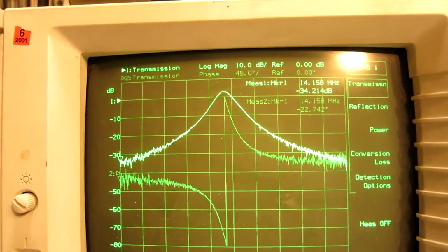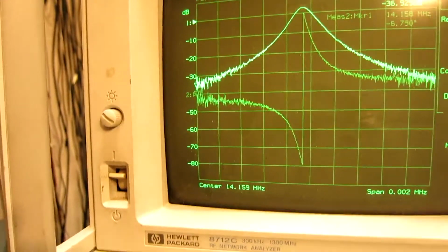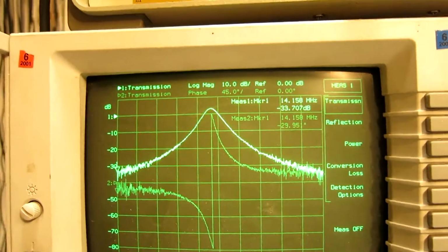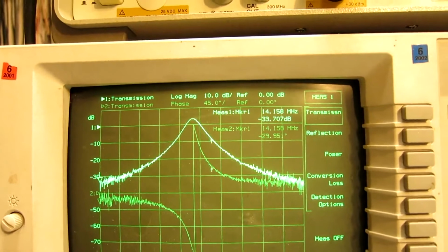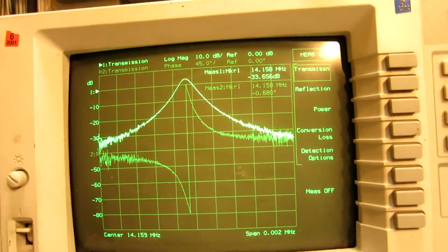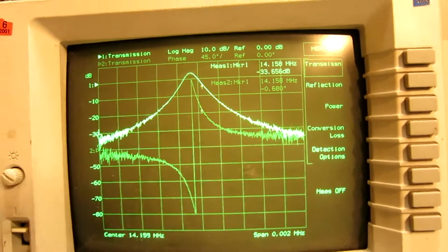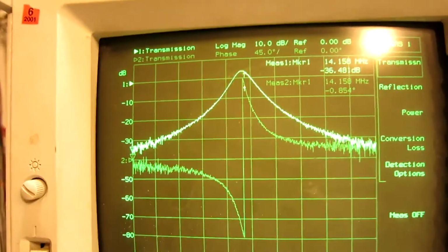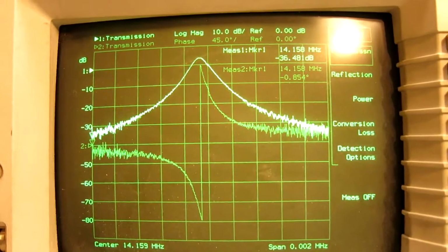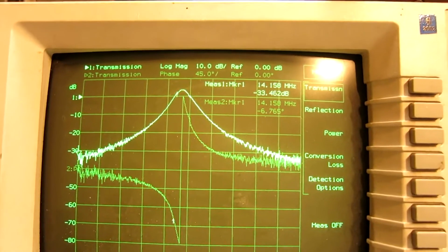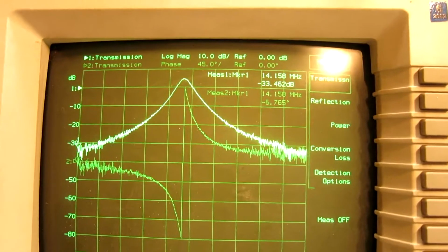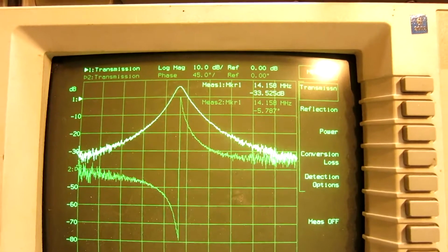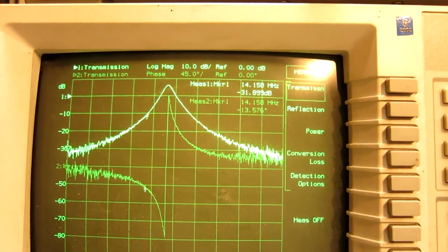There is positive feedback. 10 decibels on one of the attenuators, but there is also 5 decibels on the other one. So I increase the signal, meaning I increase the feedback. So this is the classic Q multiplier.